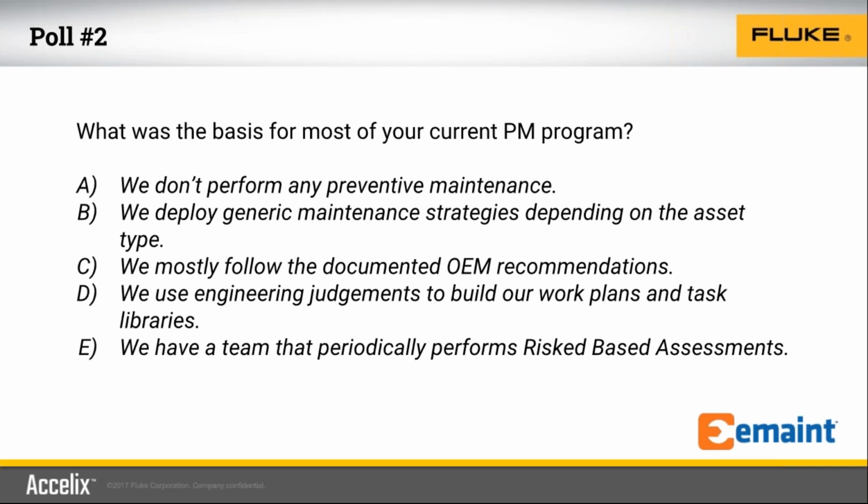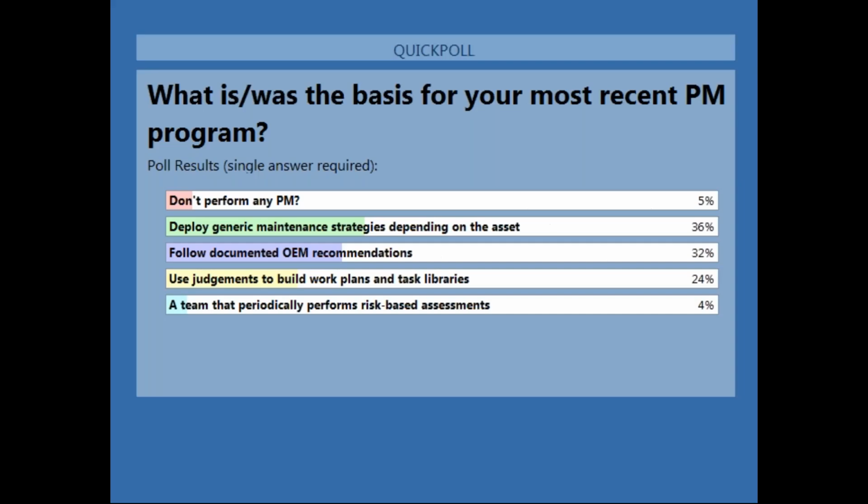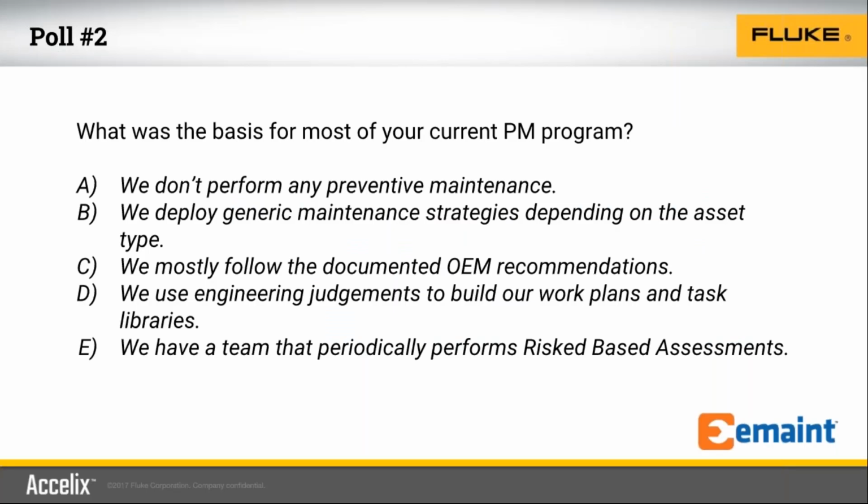So we're going to talk about a few different levels here as we go through this, but essentially if you're not performing preventive maintenance, that may not be bad, because in fact you can't really perform preventive maintenance on assets that are continually failing, because you have to get them restored first, and it's pointless to do PMs on assets that are constantly failing, right? So there has to be a restore point, and we're going to look at essentially what are the consequences here, and what are the risks surrounding that particular asset. Is it something that we really should be performing preventive maintenance or worry about?